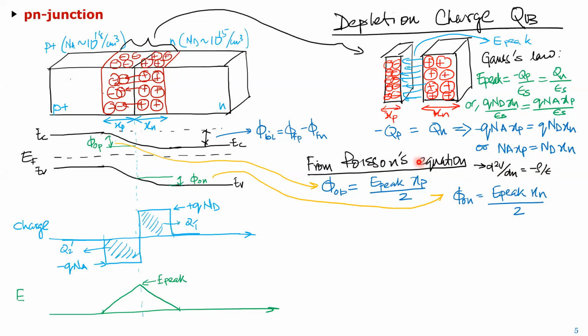But again, the reason we are telling this is we're trying to find out what is the amount of charge which is enclosed in this. That's what we are doing all these experiments and all this analysis for. And the way we are trying to do that is trying to figure out after this depletion stops, what is the length? And I know the charge density because I know what the dopant concentration is. I'll just multiply that with this and I know the total charge. Okay, and that will be useful when we do the threshold voltage calculation. That's why I'm showing you this. Again, if you don't follow all this, just know the final value for it.